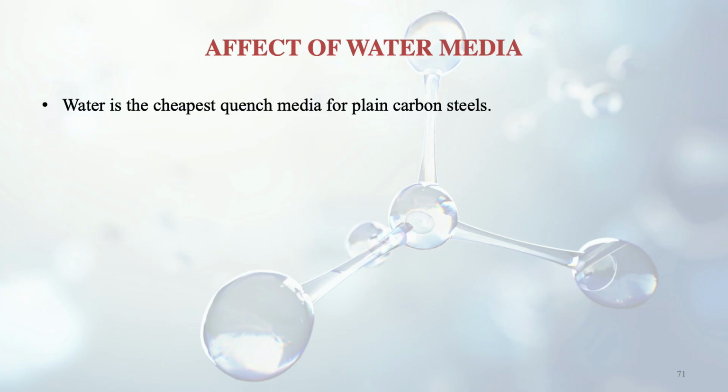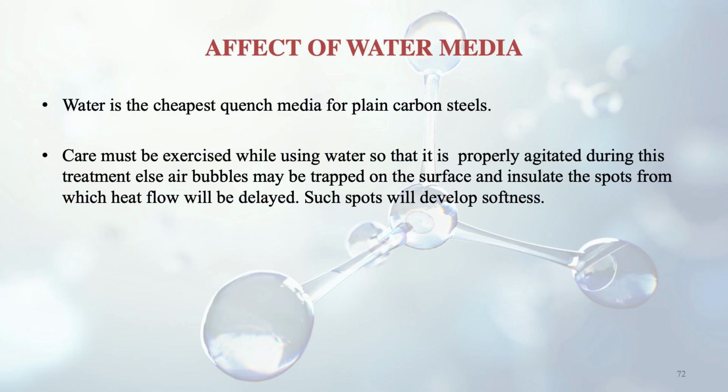Now I discuss the effect of water media. What happens when water is used for the quenching process? Water as such is the cheapest quench media for plain carbon steels, but care must be exercised while using water. Certain precautions have to be taken. It has to be properly agitated during this treatment, else air bubbles are formed and they may be trapped on the surface and insulate the spots, from which heat flow will be delayed. Such spots will then result in softness.